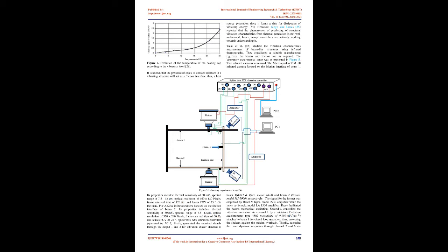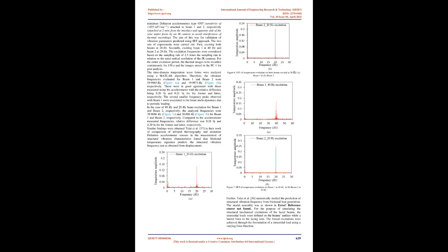Cardone et al. [49] used IRT to perform heat transfer measurements on a rotating disc in the laminar, transitional and turbulent flow regimes by making use of the heated tinfoil technique and by measuring temperature gradients. They observed that the use of this technique was advantageous on account of its relatively good spatial resolution and thermal sensitivity, and because it facilitates the recording of measurements down to very low local Reynolds numbers.